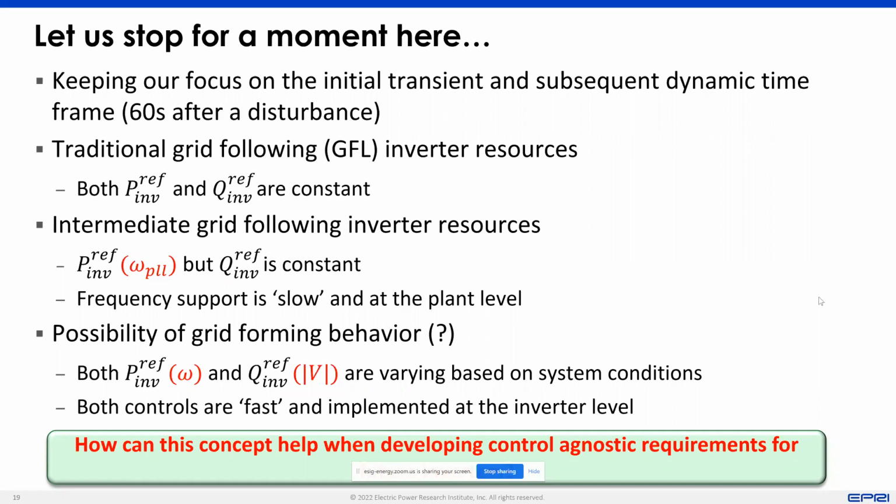Now, most of the time, as you have an increase in load, because the load is also electrically connected, or maybe there is some constant electrical characteristic for it, you will see a phase angle reduction, which will cause a frequency drop. But that characteristic also changes if the load characteristic changes. If you have power electronic load, variable frequency drives coming into the system, and the characteristics of the power electronic load is serving its own objective, the way the phase angle changes is still a topic of research.